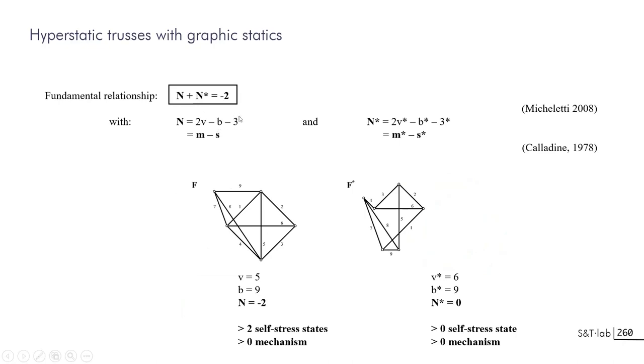the number of equilibrium you have. This is done for, on one side, the form polygon, and on the other side with the force polygon. And this is equivalent also to another system in which we have the number of mechanisms appearing and the number of self-stresses appearing in the equation.